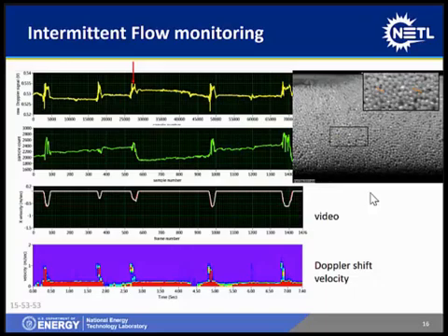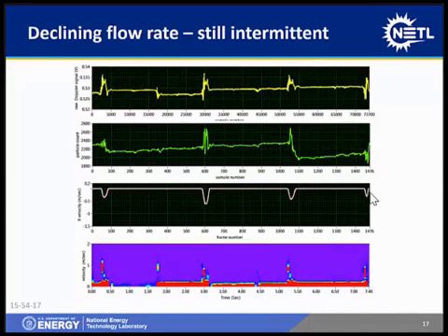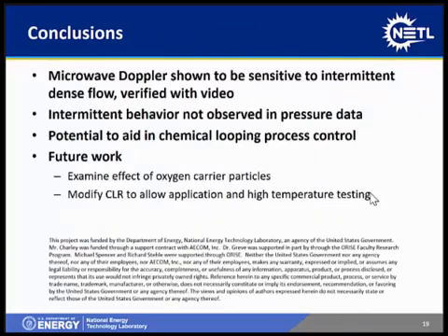And finally, down here we have the short-time Fourier transform. This is 1 meter per second and this is 2 meters per second, plotted as a function of time. The places where we have significant velocity extracted from the short-time Fourier transform line up very nicely with the, all right, this is another one slightly later in the flow sequence where you see that the flow is more intermittent. Once again, the velocities are in reasonable agreement between the Doppler measurement and the video measurement.